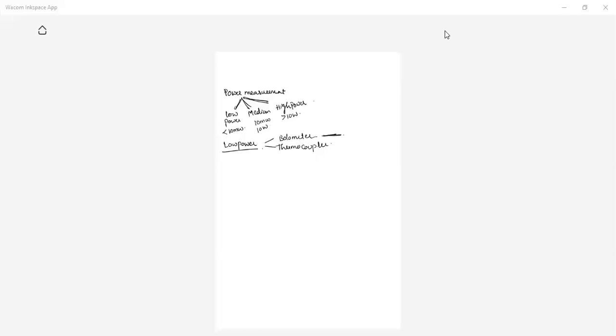What are thermal principles? When microwave power falls on the bolometer, the microwave power is converted into heat and its temperature changes. In turn, its resistance changes. The change in resistance changes its voltage. So that is the principle of bolometers. This is the procedure generally used in bolometers.